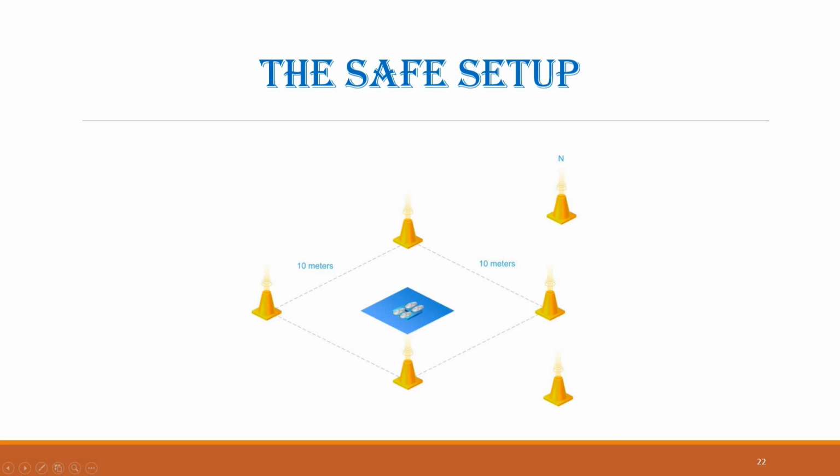This arrangement offers clear reference points that help you stay aware of your surroundings and maintain proper positioning. It also plays a crucial role in safety procedures. For example, if the drone initiates a return to home function, it will land within this designated area, which has already been assessed and controlled for safe operation.